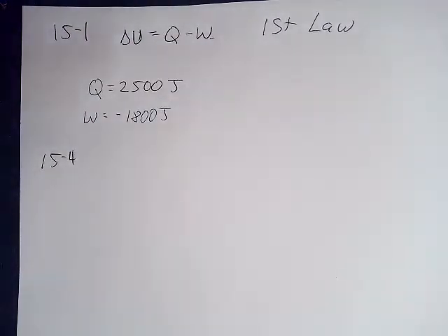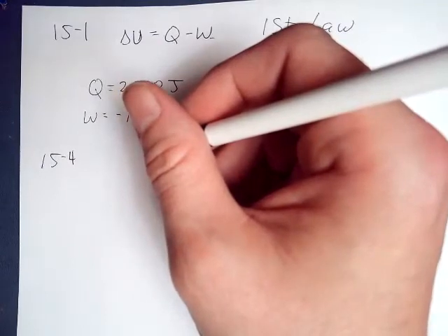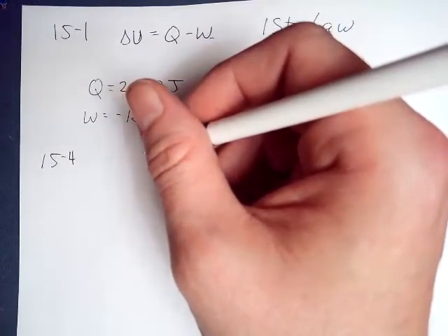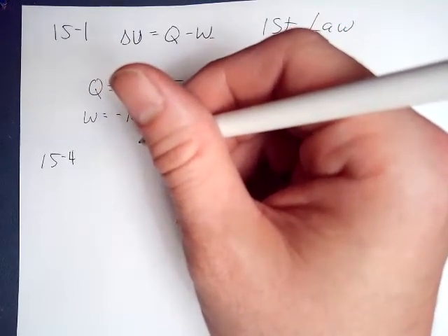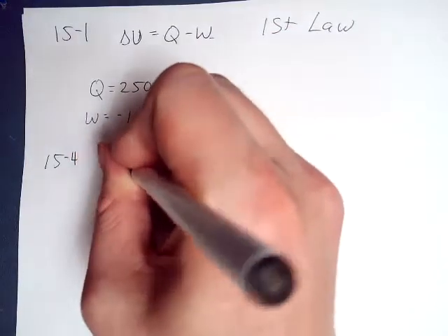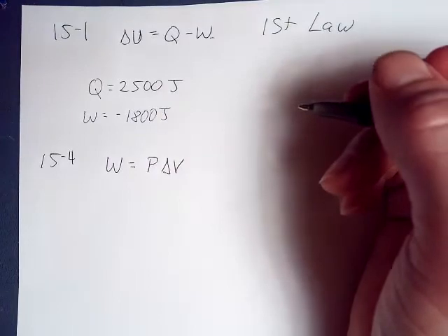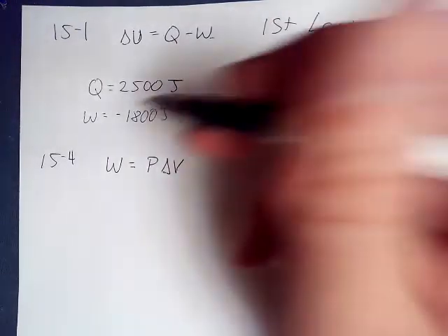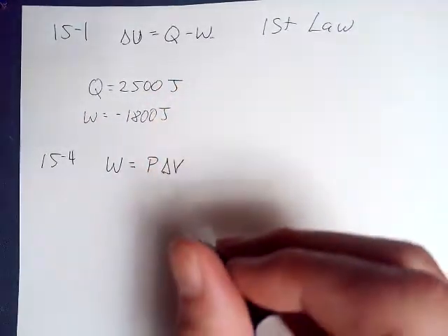Now, this is such a big topic, and we can only really barely get into calculable things without getting into calculus. And one of those is what they call an isobaric process. Isobaric refers to pressure. So if you're changing a system and you're keeping the pressure the same, then the work we can define as that pressure times the change in volume. This is isobaric, and it's really the only situation where we don't have to use integrals and stuff like that.